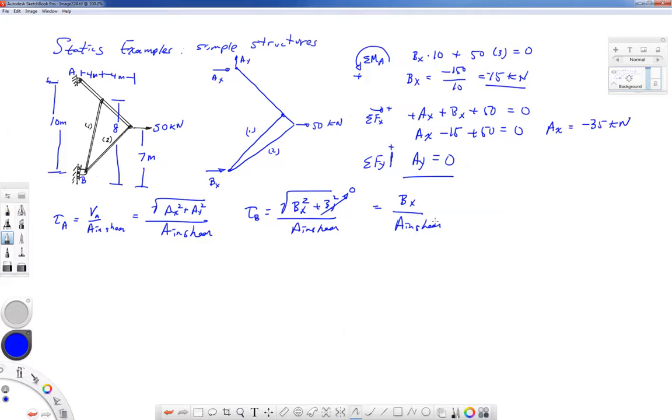Well, if we want to find the stresses in the two force members, the axial normal stress would be the force divided by the cross-sectional area, which I'll just note like this. And we might be given the dimensions or the area of the bar. So we need to find the forces in bars 1 and 2. In order to do this, we should draw a free body diagram of the pin.